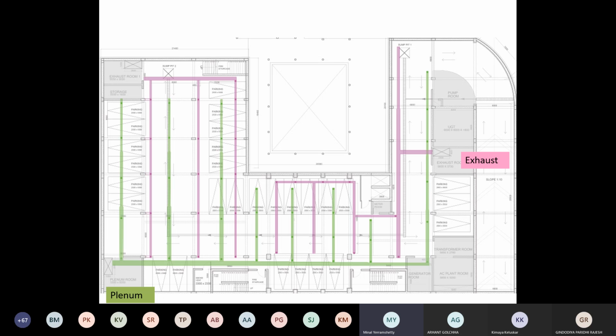And then finally A4, which is right next to the plenum room, is the thickest one because now it is carrying the volume for all the four rooms. Are we clear now? That's the reason why my volume goes on increasing as it comes towards the source, because I am having more volumes. Okay, because various bays have to be given equal number of that kind of volume.